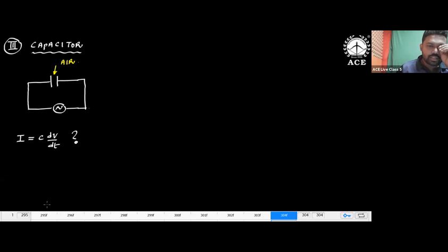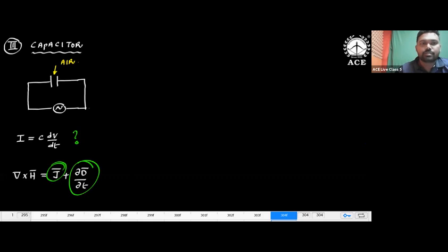Displacement current, because of the displacement current, charge distribution. Okay, charge induced displacement. Okay, very good, very good. Due to the charge, yes. See here, we know from Ampere's law, curl of H is equal to J plus dou D by dou t. That means the magnetic field is due to flow of charges and also due to the time varying electric field.